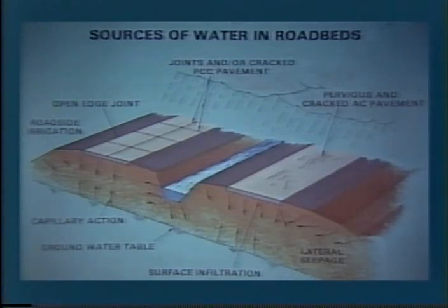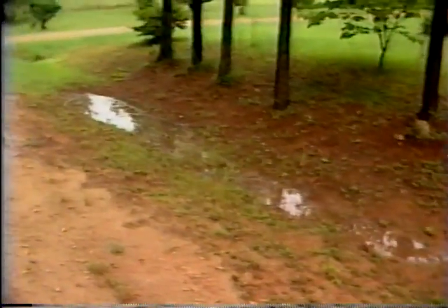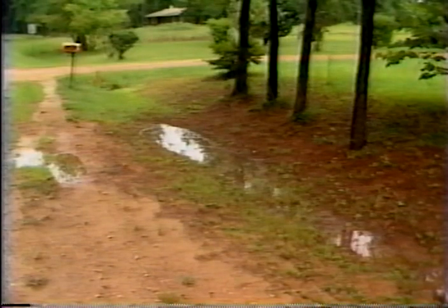In addition to carrying surface water that drains off the roadways, ditches also can prevent underground water from seeping into the subgrade and base materials of the road. Keeping the ditches lower than the roadbed causes underground water to flow along the ditches and not up into the roadbed. Here is a ditch where the original flow line has been obstructed by sediment and debris. This situation will occur over time on many roads due to erosion and litter.